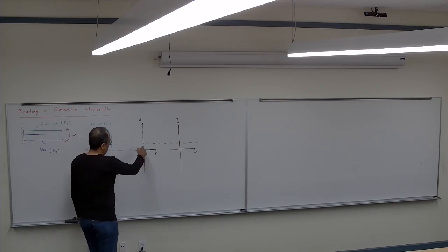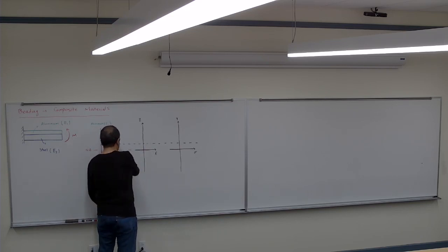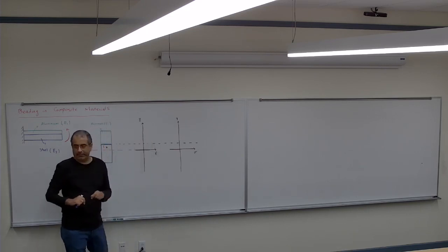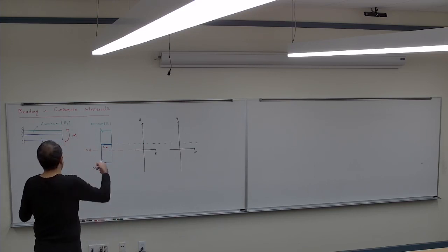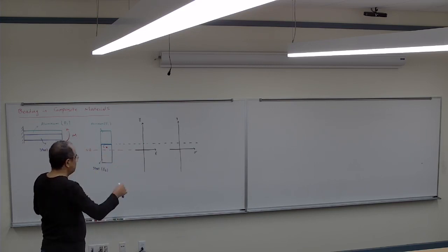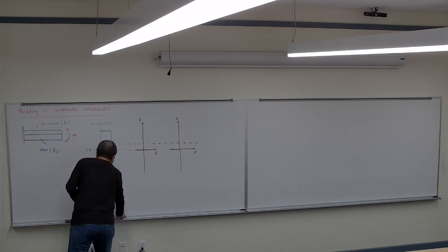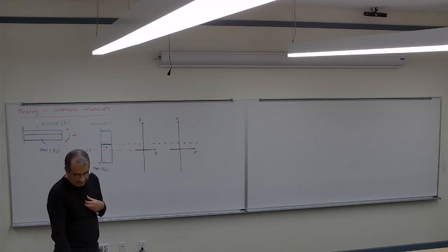Where is it going to be zero? At the neutral axis. So I know it's going to be zero there, and then it's going to be stretched at the very bottom. Sorry, going up, so it's compressed at the very top and stretched at the very bottom. Correct? If it's compressed at the top, is it going to be negative or positive? Negative.